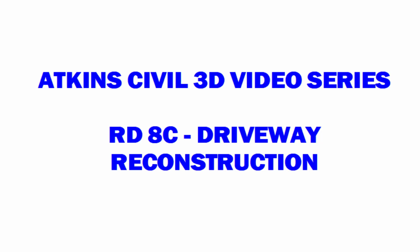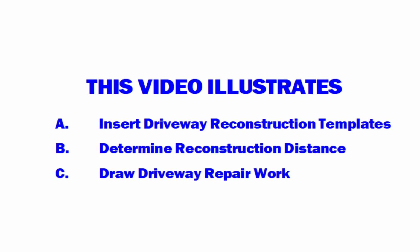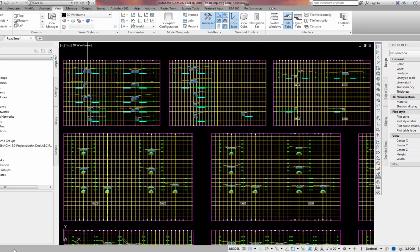Atkins Civil 3D video series, Road 8C, Driveway Reconstruction. This video illustrates A. Insert driveway reconstruction templates, B. Determine reconstruction distance, and C. Draw driveway repair work. Driveway templates are used to determine the minimum length of driveway reconstruction work to prevent vehicle drag.